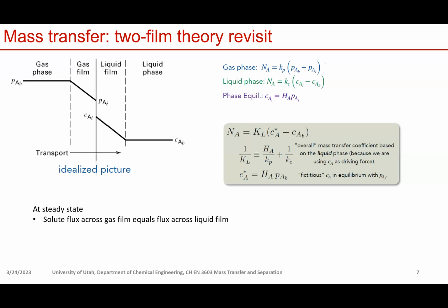So then in the liquid phase, we know the bulk concentration, but in the vapor phase, right? So the driving force is some type of composition difference between the gas phase and liquid phase, right? Here we pick concentration to denote the composition, but in the gas phase, we cannot directly subtract C_AB from P_AB, right? Because they have different units. You cannot do that. So somehow we can use Henry's law here to convert P_AB to a fictitious concentration, right? Just convert. So it has the concentration unit. Then that way we can calculate this difference, right? And that will be your driving force.